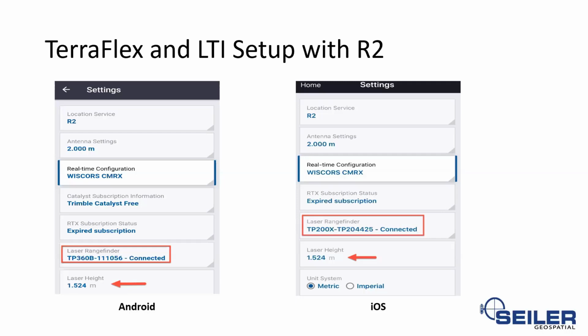Sure, Jay, I can. Historically, we really only needed a lat/long position for GIS, right? Elevation wasn't all that critical in a lot of cases. Well, as position accuracy increases, our desire for good elevation data is increasing. So the GNSS can give you better elevation, and now the laser can carry that good elevation with you.